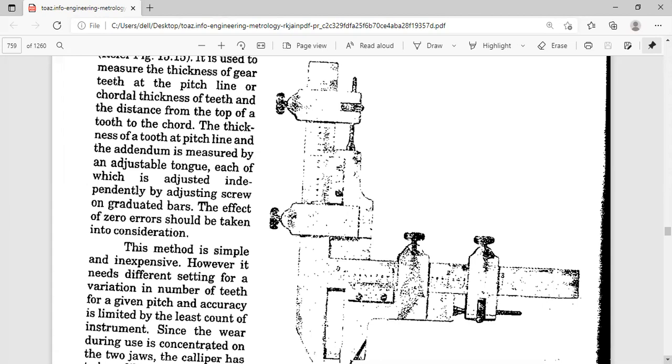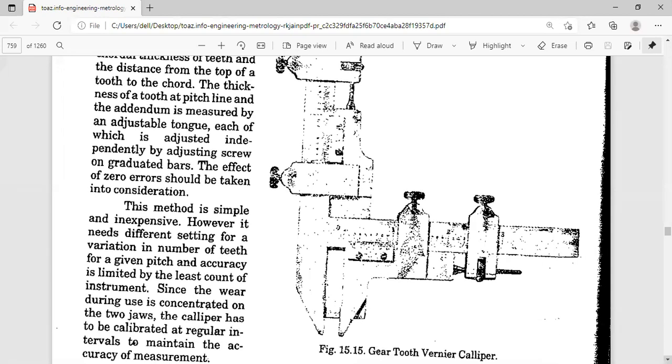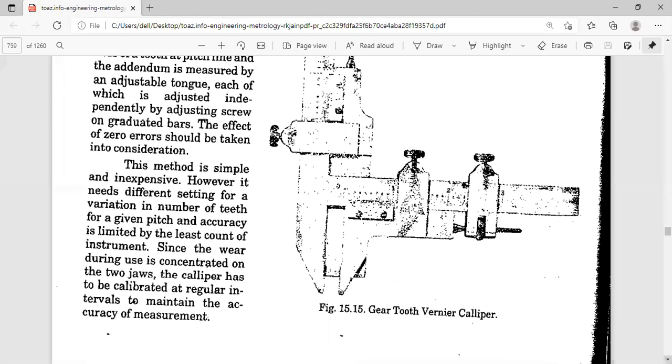You know least count, from intermediate, is the least possible value that can be measured by the instrument, and least count is 1 MSD minus 1 VSD. You should know that calculation because they will ask in the lab also. Just try to refresh that knowledge regarding least count.